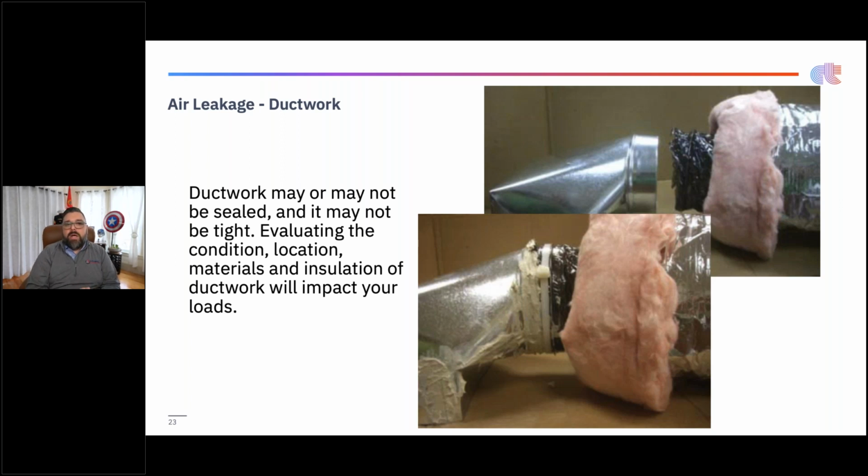load, right? A properly sealed boot and flex fitting you can see on the front side here versus something that could be easily disconnected, unsealed, not sealed to the ceiling. Where that boot hits the floor or the ceiling, those flanges should be sealed as well to slow down the infiltration through that ceiling and floor from unconditioned space, right? So that all impacts the duct losses and gains, which impact the load. And I've seen this up in an attic easily be a half a ton to a ton additional sometimes when it's outside the building envelope.